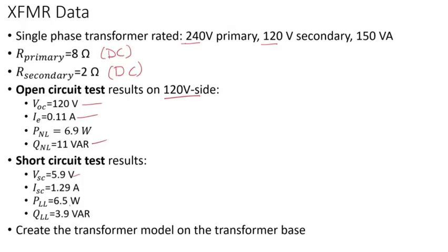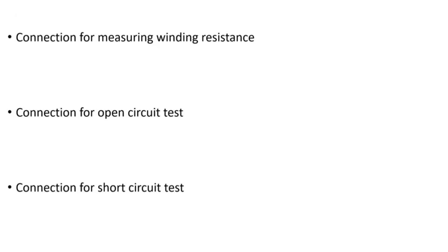So we want to create the model from this, and this is really a test that the manufacturer will perform, and that's how they would come up with the core losses, load losses, and also the impedance. This is a small transformer, but the same thing can be applied to any transformer. I'm picking single phase because the focus is more on the concepts, and once you understand the concepts, you can apply them to three phase easily.